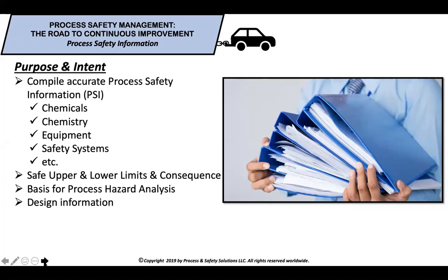So what are the process safety limits? Limits to the process itself, not limits to the equipment, not operating limits, none of those things. This information should be the basis, like we said, for process hazards analysis. Typically, we can look at process safety information as design information. What is the information that we used first to design the equipment, and how the equipment is actually designed.